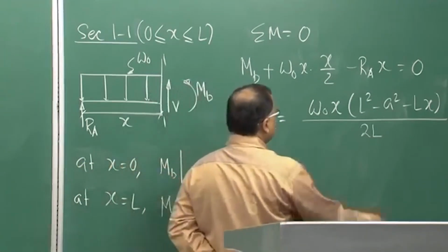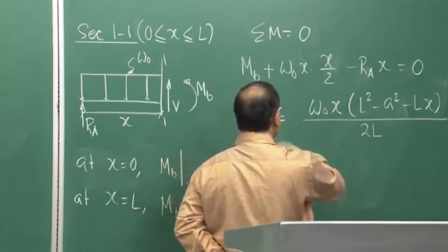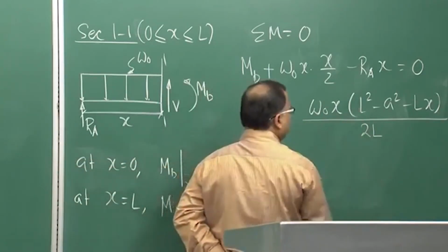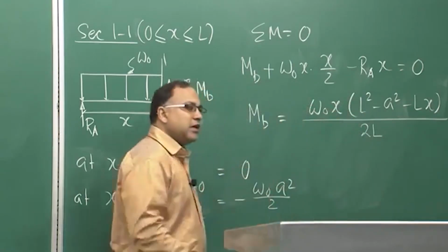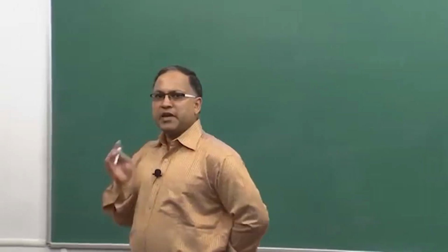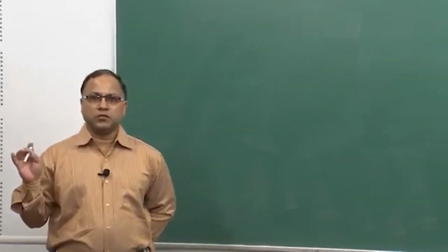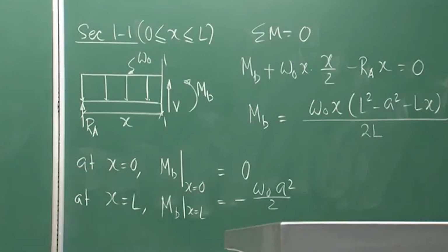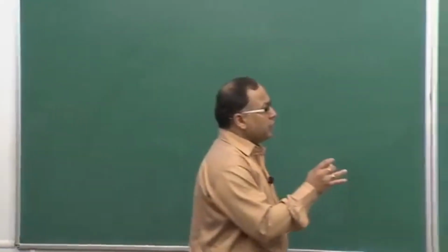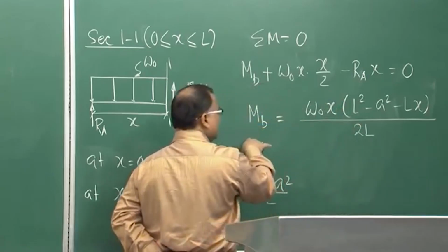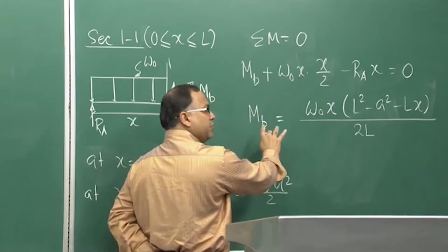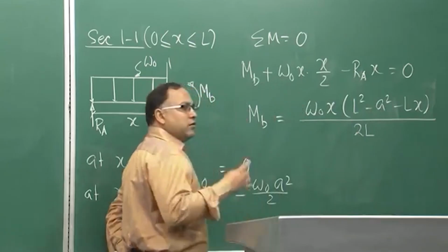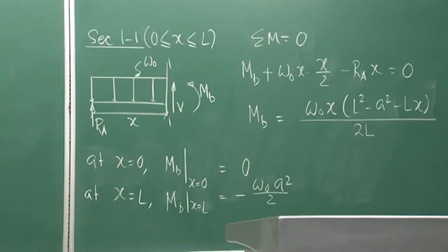Okay. If you put M B equal to 0 in this expression, then from this equation it is very much clear that there are two values of x where the bending moment is becoming 0, yes or no. One point already we have obtained, that is at x equal to 0, but another point is yet to obtain, yes or no. So, if you put bending moment equal to 0 here, at x equal to 0 the bending moment is becoming 0, that is already obtained, but another point you must get from this where again the bending moment is 0, right. So, let us find out that point.